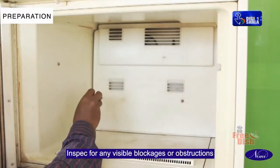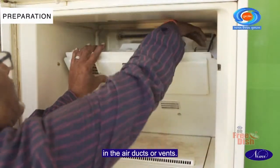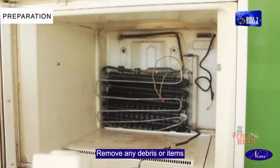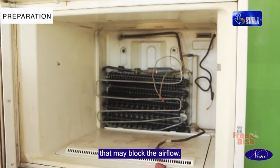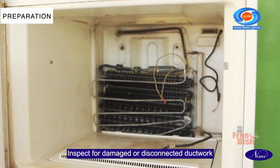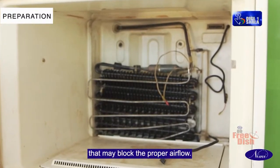Inspect for any visible blockages or obstructions in the air ducts or vents. Remove any debris or items that may block the airflow. Inspect for damaged or disconnected ductwork that may block the proper airflow.